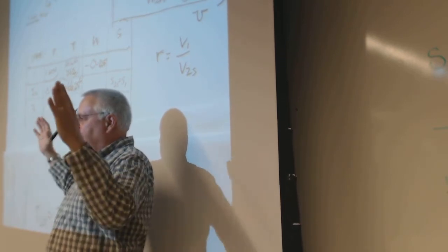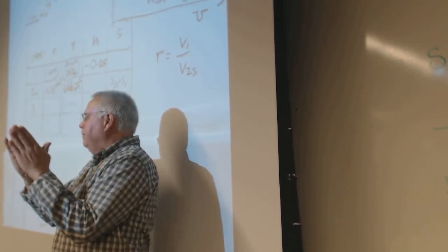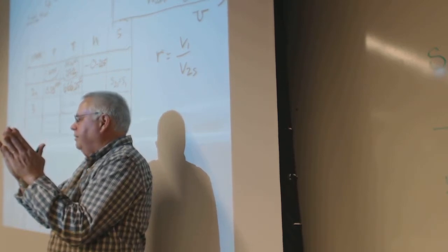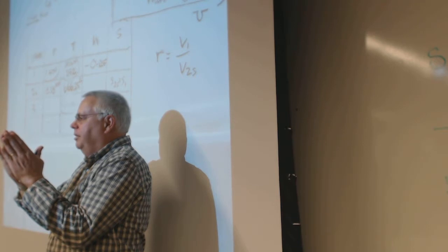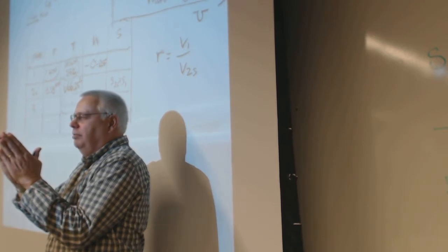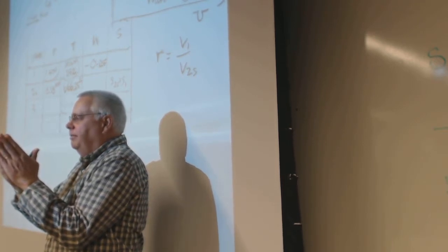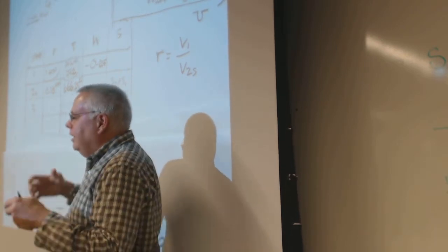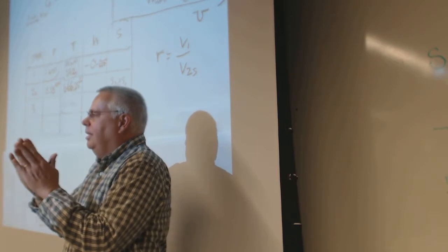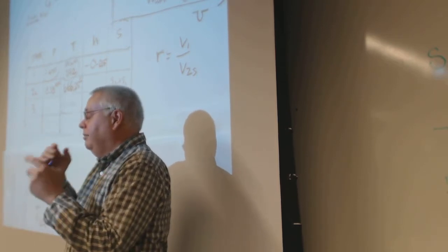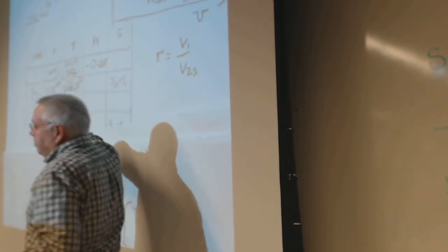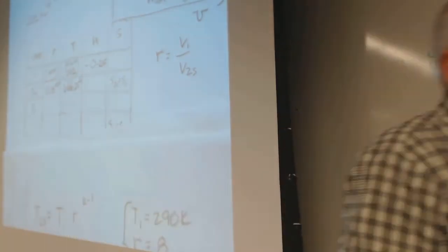If nothing else happened, going to 1/8 the space would make it go up 8 times in pressure. But the fact that it also heats up when you compress it means you had to put the work into compressing it and also the work into making the heat. And how much work did you do? It's this times the C sub T. We'll get to that one in a sec. Let's chase the temperatures around.